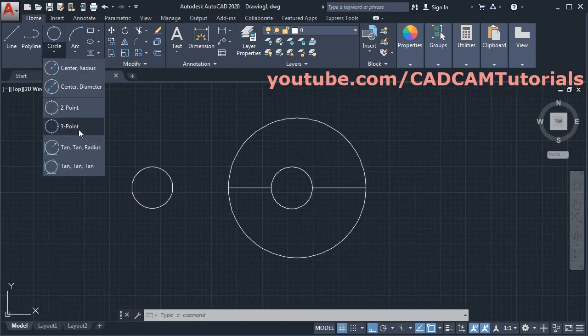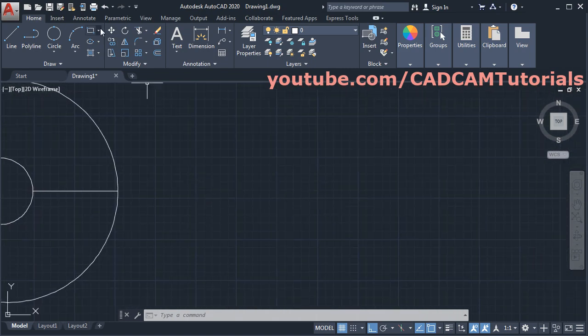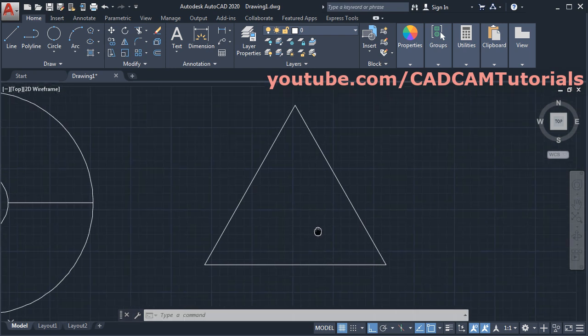Then next is 3-point. Suppose I will create one triangle using polygon command. I will give number of sides as 3, enter. Then I will use this edge method. Then specify first endpoint, take your cursor away and click. Suppose I want to create a circle passing through 3 midpoints of this triangle.